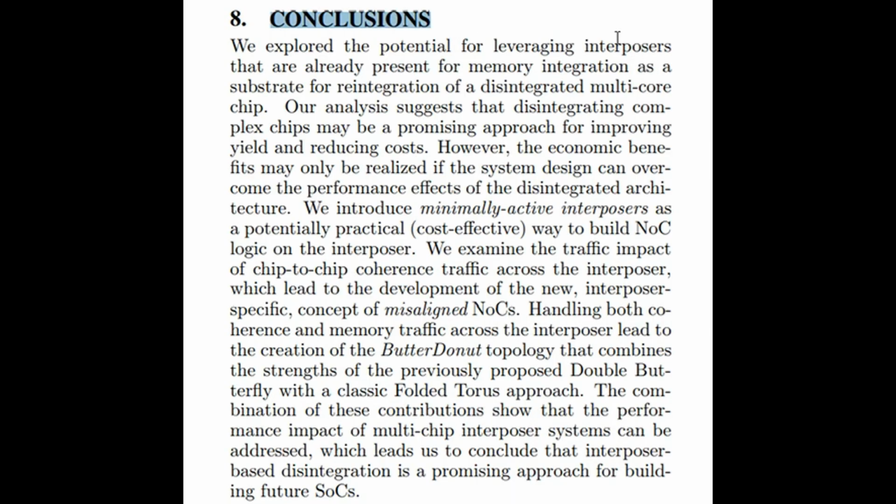performance. And finally, moving on to the conclusion of what is a truly fantastic paper, which introduced the concept of minimally active interposers as a potentially practical, cost-effective way to build network-on-chip logic on the interposer, which, while examining the traffic impact of chip-to-chip traffic across the interposer, led to the development of the new concept of misaligned network-on-chips, which then led to the creation of the ButterDonut topology. The combination of these contributions showed that the performance impact of multi-chip interposer systems can be addressed, leading the researchers to conclude that interposer-based disintegration is a promising approach for building future system-on-chips.